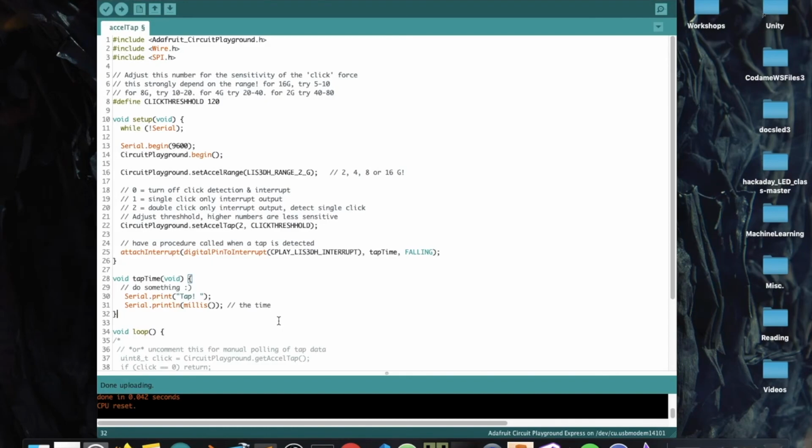Note that you can put literally anything inside your interrupt function, but keep in mind that interrupts will block, i.e. interrupt, normal execution. So normally what you want to do is something quick. You can just change a global variable, defined as a volatile variable, so that Arduino knows that it might change outside the control block in which it appears, for instance, so that your main loop knows you've detected a tap. We'll walk through this in a second.